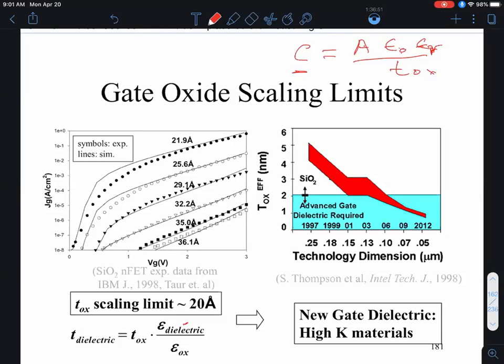And we'll see today, when you look at MOSFETs, that the current of a MOSFET is proportional to the gate capacitance, Cox. And that kind of makes sense because the larger the value of Cox, the more strongly the gate is coupled to the channel, and therefore it can induce more carriers in the inversion layer for a modest gate voltage. And that's what you want, because you want to be able to operate the device at as low a voltage as possible.